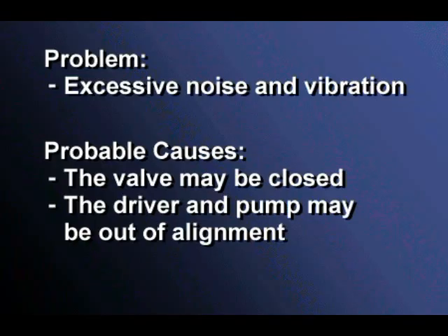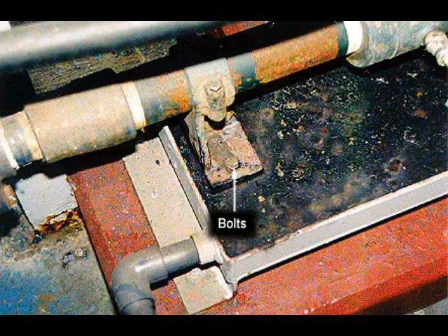Make sure all of the valves are open and there is adequate flow to the pump suction. The driver and pump may be out of alignment. Check that all pulleys are mounted and aligned onto the shafts, and the belts are properly connected. Make sure the couplings are firmly connected. Or the pump may have loosened on its mounting. For this, tighten the bolts or add grouting to the foundation.